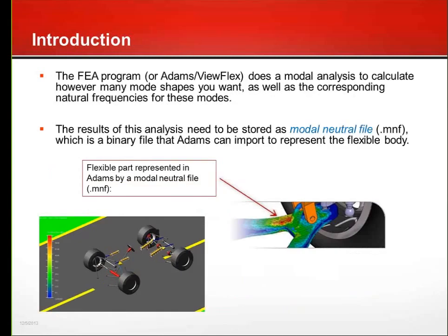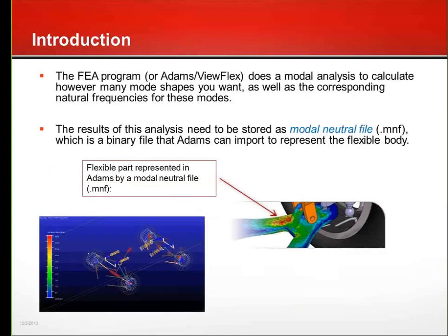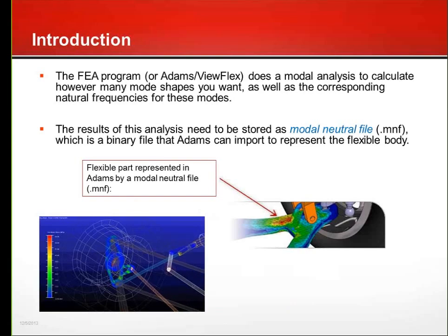Okay, so like I mentioned, the FEA program does the modal analysis, writes that out to a modal neutral file, and that's what you import into Adams as the flexible body representation.